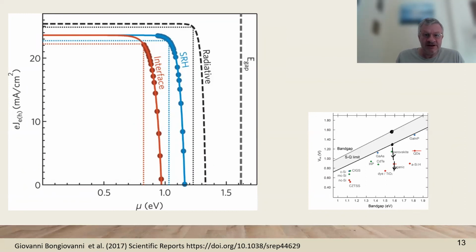So this is mainly seen in the photovoltage, but it will affect also the fill factor, as we said before. And then from the gap energy, we go to the radiative recombination, including Shockley-Read-Hall decreases further, and for interface recombination it is further decreased. And in each case, we can see that the power conversion efficiency is the area of the square.